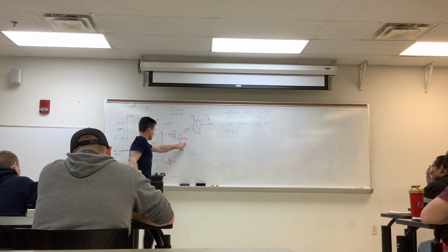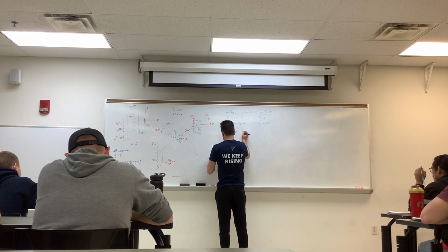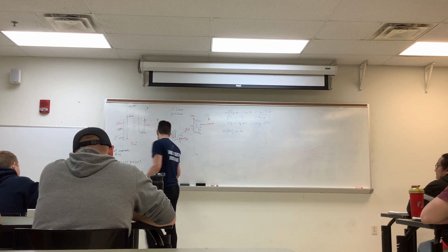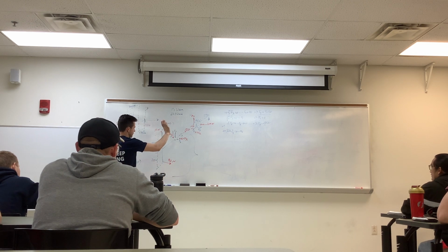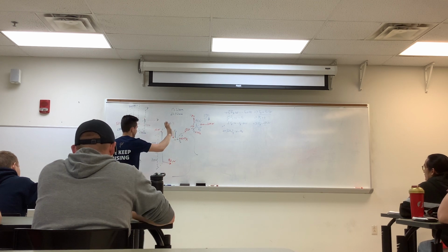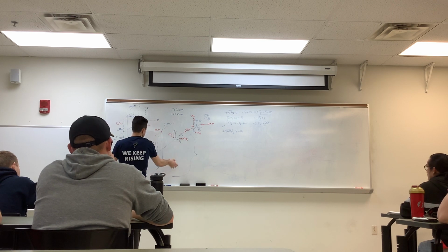We have this negative Mx opposing what we have assumed as positive, so negative Mx. Interpreting what causes the moment about point O about the x-axis, thumb along the axis here, curling our fingers, what causes this entire structure to rotate this direction, you could say.